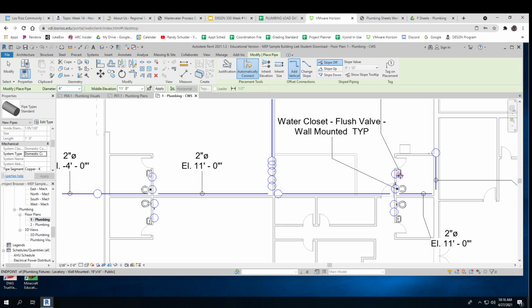And so you need that hot water super hot somewhere. So if my hot water heater is sitting here, I've got to get it up to 135 or 140 by the time it gets over to here to mix with my cold water. So it's not as efficient in general to have a hot water heater and then put your little point of use on. However, point of use can really pull too much energy all at once for your electrical.